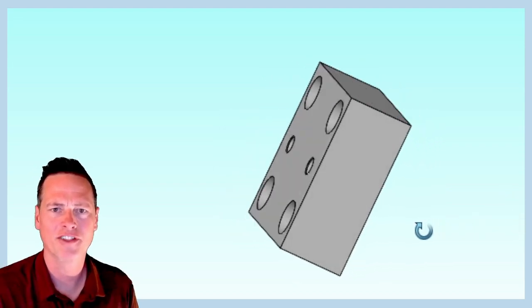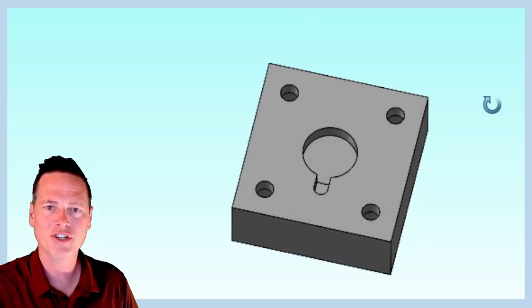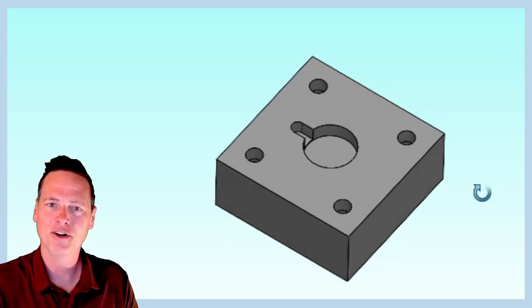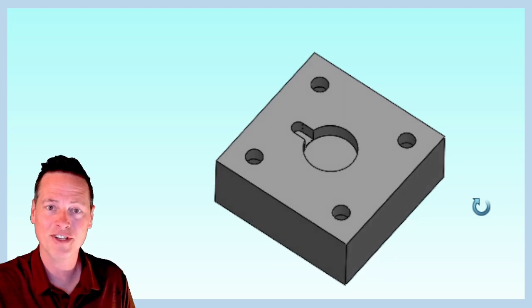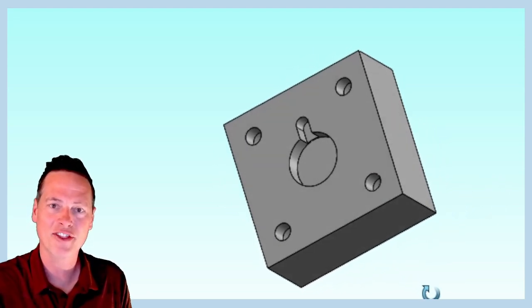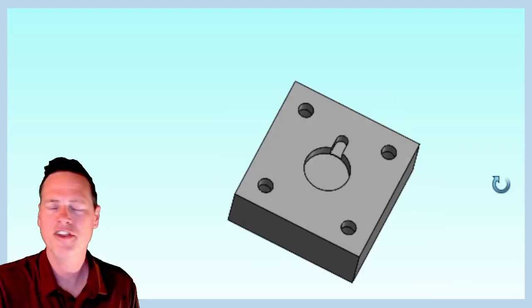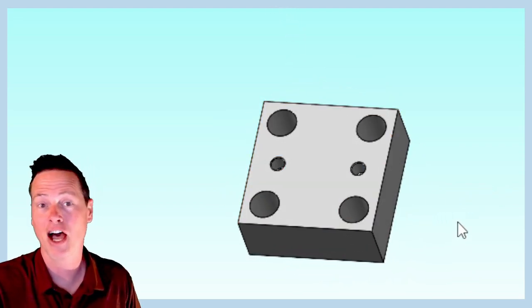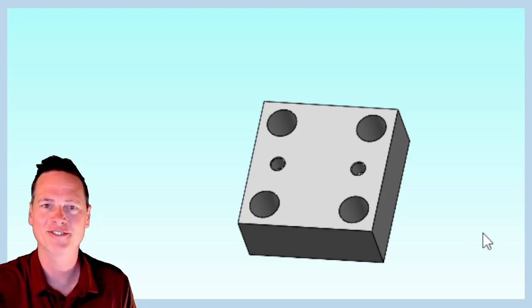Let's have a closer look at the interface on the bottom here, where we have some other features that really sure seem to be like locating features for this interface. I would say that cylindrical pocket in the middle sure looks like a locating feature, like a secondary datum feature, and the notch looks like another locating feature to control the rotation, a tertiary datum feature. On the other hand, it doesn't seem like we have any other really special locating features on the top. So let's just go have a look at this assembly where this part's being used.